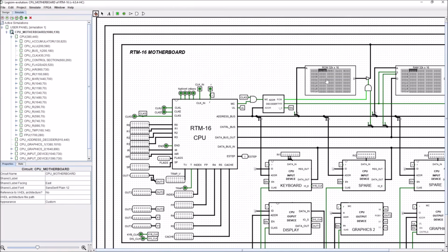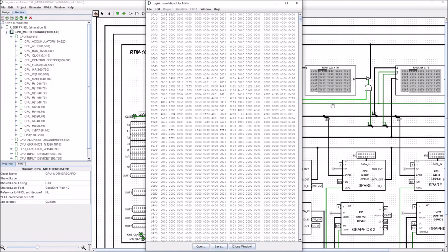So that's going to be within the ROM. This is the ROM here. Now the very first 1, 2, 3, 4 values here, remember the first ones are used to set up the stack pointer, and then the next one's just a jump to address 8000. So it's saying jump to the address allocation 8000, which is this memory location here in the RAM, which is the first address of the program. So that's the very first thing that happens in our computer when we first start it up and we run a piece of code.